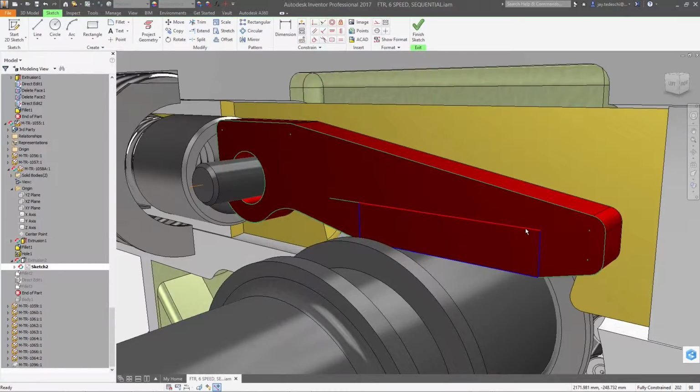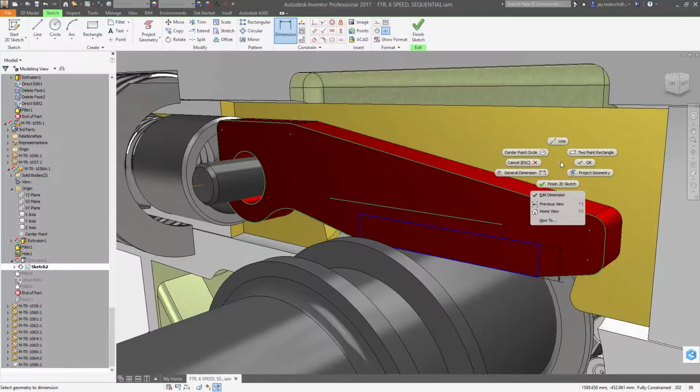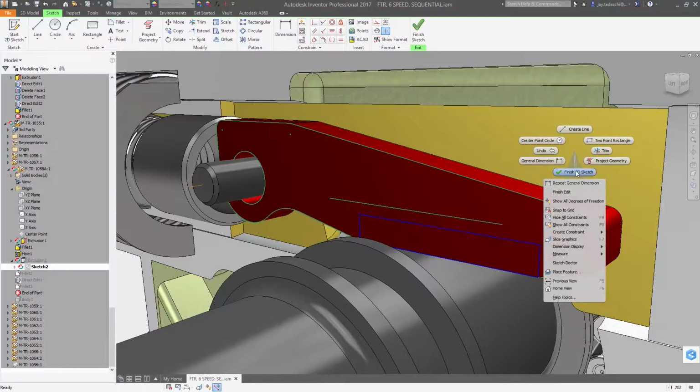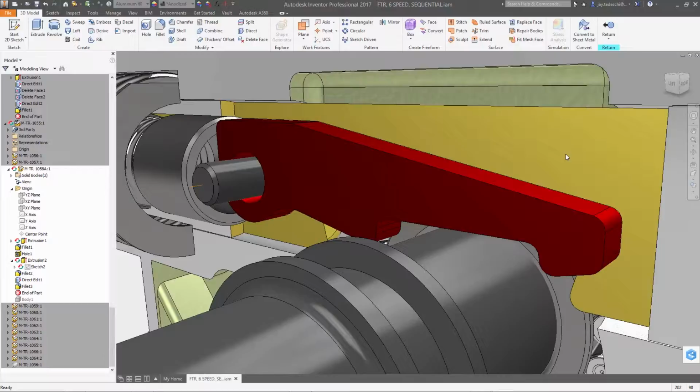When you need to change a complex sketch, Relax Mode lets you dive right in without worrying about which dimensions and constraints are already there. Manually moving sketch features around or adding new dimensions or constraints automatically deletes any conflicts, so you can move forward in the design without dealing with warnings about over-constrained geometry.